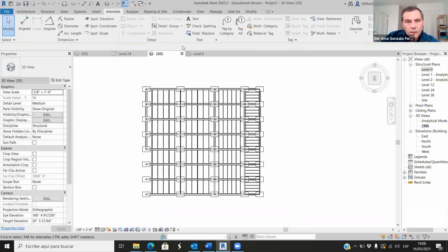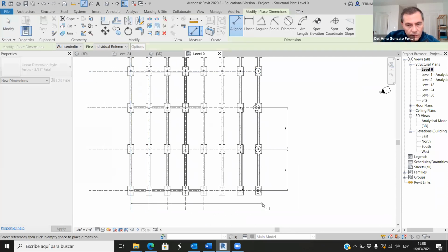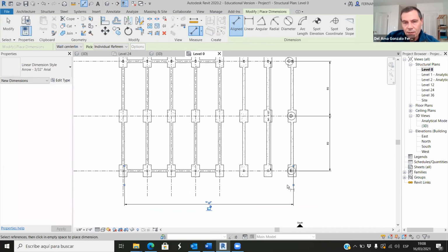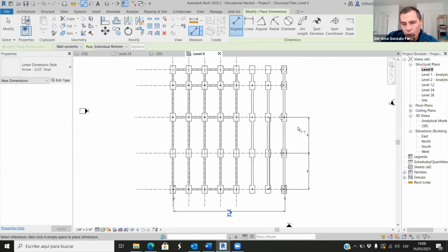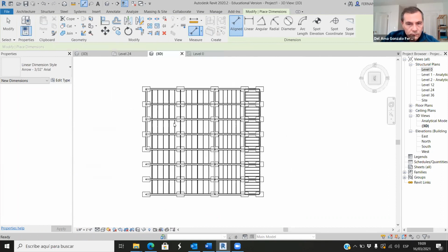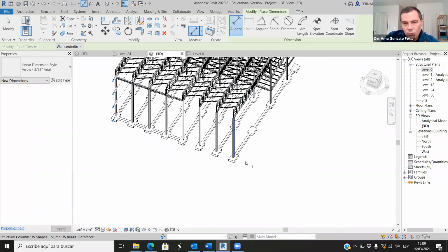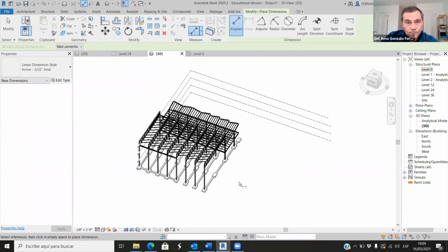How many bays do we need? But if you take a dimension, if you place a dimension from this point to that point, well, now it's 84. It has to be more than 84, so probably we need one more here, okay? So with one more truss, one more column here, then we can have this basketball court.